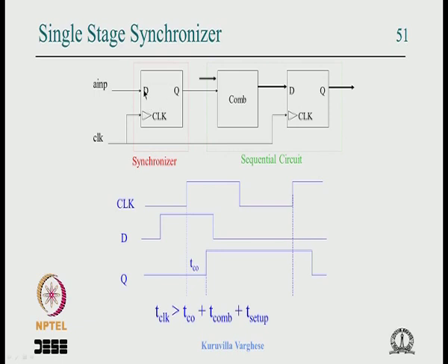We have put a flip flop and said fine, now the data appears with a delay and the setup time is met here. But what about this flip flop, okay. Now the data at the input of this flip flop has no relation to the clock here. So now this can get into metastability. So we have not solved the problem, right. Looks like this is a kind of cheating, you shifted the problem, okay. So we didn't solve the problem, we shifted the problem.